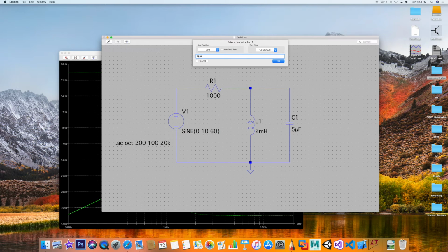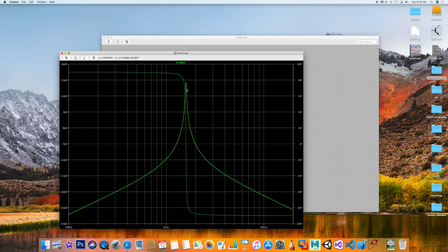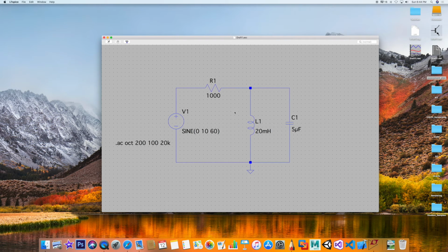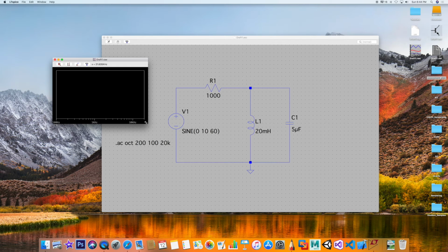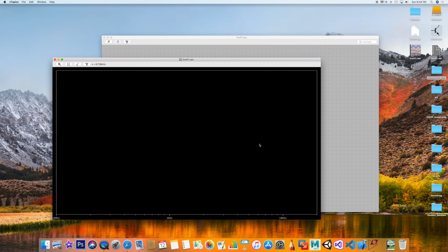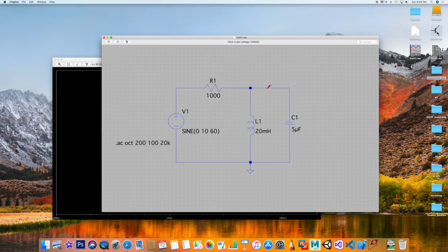you had a 20. Let's go by a factor of 10. Let's see what a 20 millihenry will do. Now remember where our frequency was. It was at 1.59 kilohertz as far as the resonant frequency, right? So let's go ahead and do this again. And you need to run it. Let's see what a change in the induction or the inductor will do. And let's do this here.